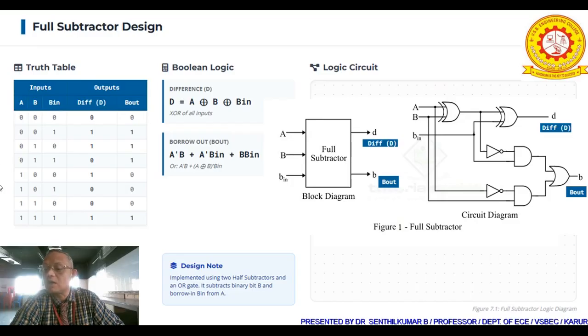Then accordingly we have to identify all the possible combinations of inputs, then we have to specify correctly the number of outputs. For every set of inputs there should be an output. It should be mentioned properly. Then we have to go for the function implementation. Function can be either SOP form or POS form, that is sum of product or product of sum.